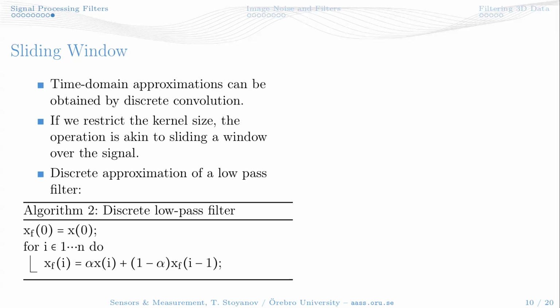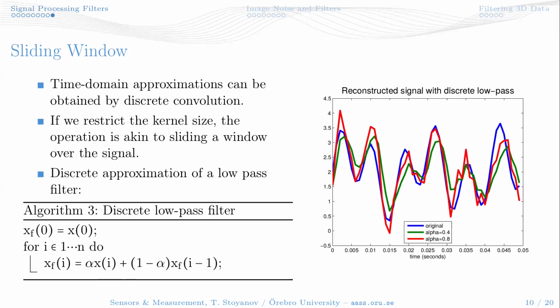Now, if you set alpha to something close to 1 but not 1, like 0.95, for example, then you would be passing through a large part of the new signal, but smoothing it out with the previous value. So you're making the signal change a little bit smoother, and this is, in effect, what a low-pass filter does as well. So here's an example of a discrete time low-pass filter on that previous signal.